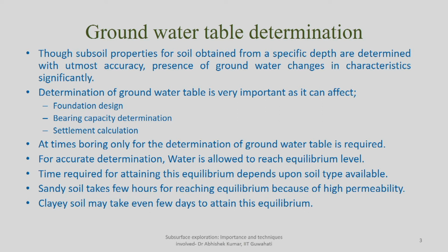Though subsurface properties of soil obtained from a specific depth are determined with utmost accuracy, the presence of groundwater table changes its characteristics significantly. You are collecting the soil sample from a particular depth and determining its strength characteristics, but whether those characteristics will actually determine the behavior of the foundation will change drastically in presence of water versus in absence of water.